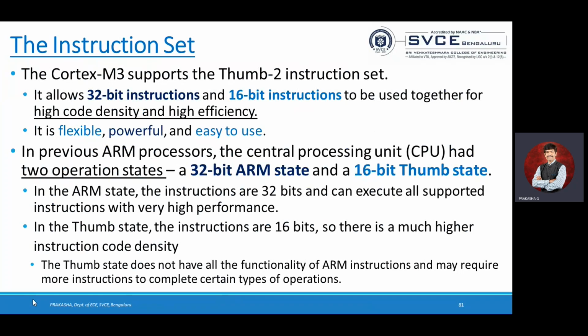All the labels should come on the extreme left side. Instructions should come with one indentation, and after that, whatever variables or registers you are going to use, you should write at the right side itself. Okay? Even if a comma is missing, it's going to give an error. Even a semicolon. Actually, we don't have a semicolon, only for comment purposes we are going to use a semicolon over there.